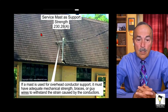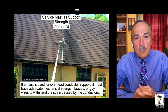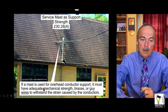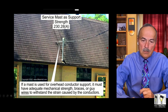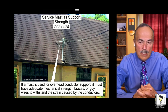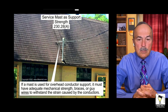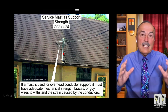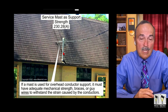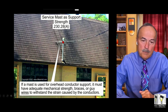All right, going to 230.28(A). Brian, this is right down the street from you, where we go mountain biking there in Ocala. And here's what it says. If a mast is used for overhead conductor support, it must have adequate mechanical strength, or braces or guide wires, to withstand the strain caused by the conductors. Well, I couldn't get any closer. I tried to get as close as I could to this house. I had to zoom in on my phone. Probably could do a better job with my 11 Pro Max phone. But there is going to be some kind of guide wire.